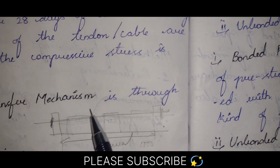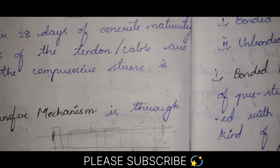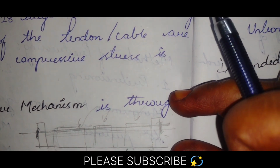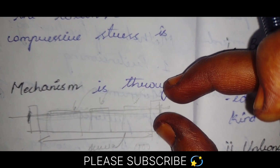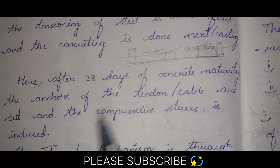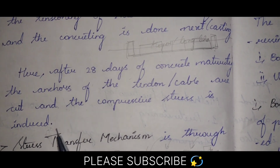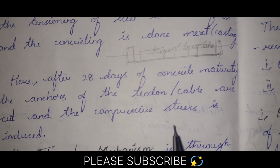After that we are pouring the concrete in each of these, and we will allow it to set. The transfer of pre-stress is usually achieved by hydraulic or screw jacks. After 28 days of concrete maturity, the anchors of the tendon or cable are cut and the compressive stress is induced. So this is the process of pre-tensioning. This is the pre-tensioning system.